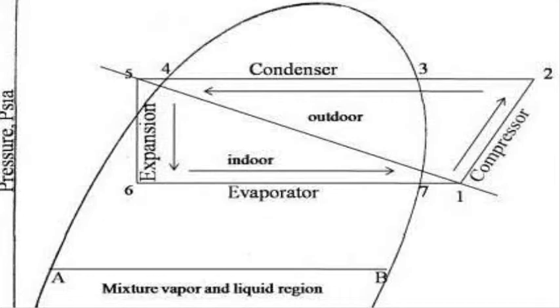As the refrigerant reaches point 4, it is 100% saturated liquid refrigerant. From points 4 to 5, it removes sensible heat from the saturated liquid refrigerant. This is where we could use a thermometer and tell how much heat has been removed. As more heat is removed, it's now in the subcooled region.